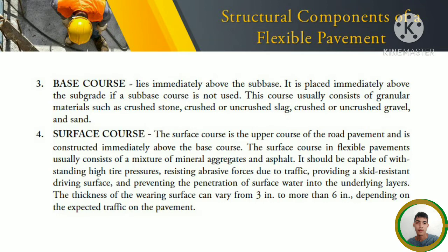The third structural component is the base course. The base course lies immediately above the sub-base. It is placed immediately above the subgrade if a sub-base course is not used. This course usually consists of granular materials such as crushed stone, crushed or uncrushed slag, crushed or uncrushed gravel, and sand.